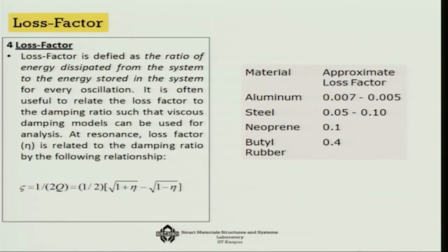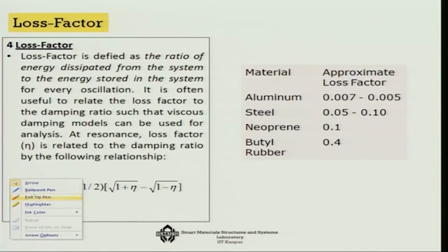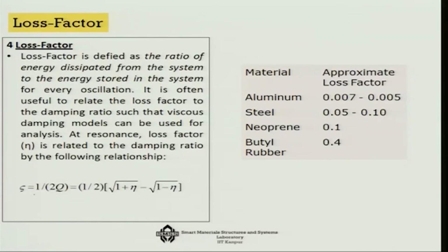While quantifying the damping, we have to talk about another very important factor which is known as the loss factor. The loss factor is defined as the ratio of the energy dissipated from the system to the energy stored in the system for every oscillation. So, if you consider an underdamped situation, and plot the response with respect to time, the response is cyclic, however the amplitude is coming down gradually.